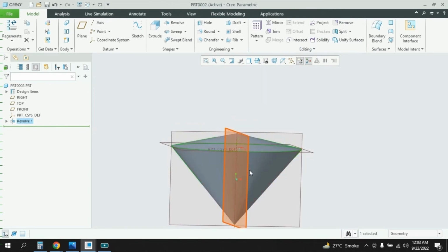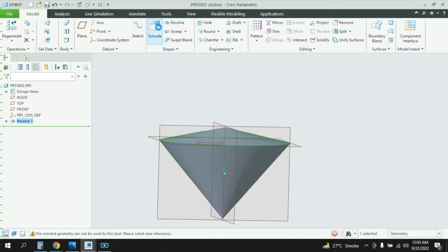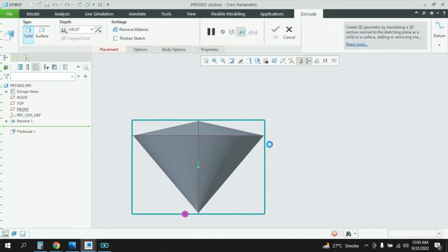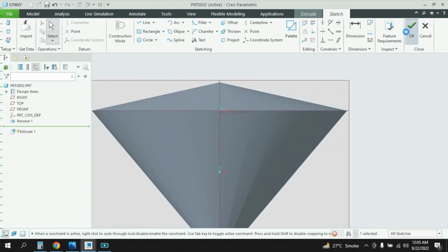Now in order to assemble this diamond inside the rain hood, I need to draw some supports here. For drawing the support, I will again use the extrude command. I will choose this plane. We will draw the support here somewhere, just so that this is in line with our rain hood body. Something like this. Now this is a closed loop. This one I will increase to 120, and this is okay. 85 should be okay, and I will click OK.